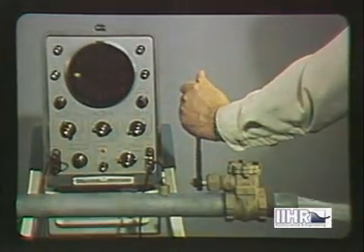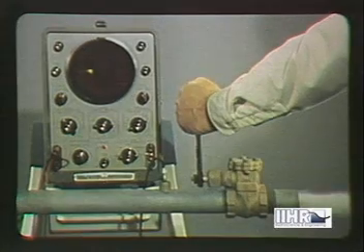The best way of preventing water hammer is to require that the valves be closed slowly enough to hold the pressure at a safe value. Moreover, pressure tanks containing air set into the line will very effectively cushion the pressure changes.